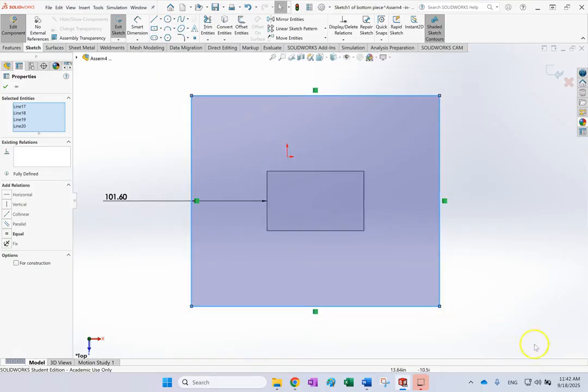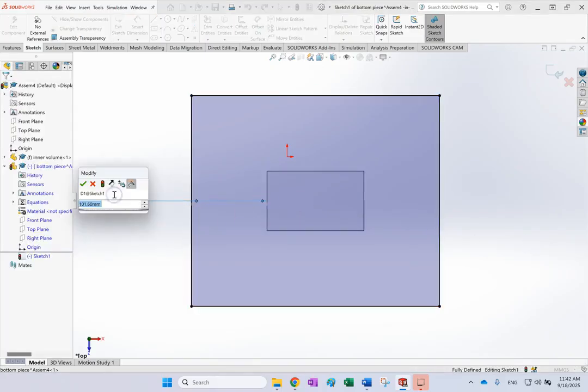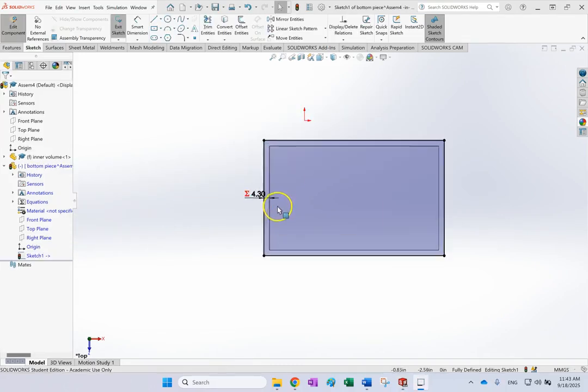first thing first, look at the unit that you have. The unit in this file is already set to mils. And this is a big number. So now I can double click on this and say equal to, and now look, I have access to the global variable t. And as soon as I OK that, there we go. It is changing to 4.3.